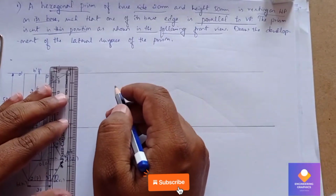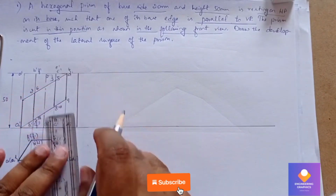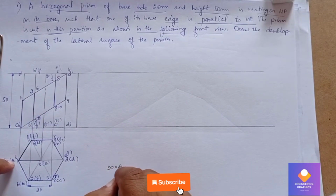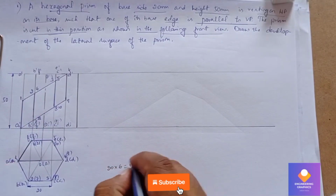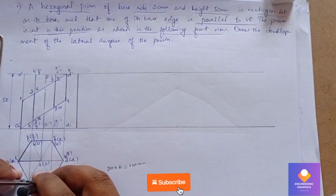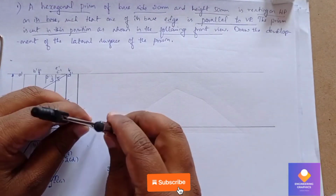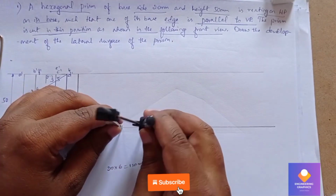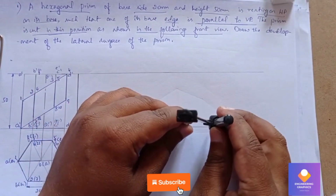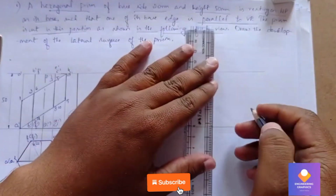We'll draw a reference vertical edge. So here the hexagonal prism of dimension 20. So 20 into 6 sides means it is a total of 120 mm. So that means if we cut the arc by considering 20 mm, total 6 arcs we have to cut here. Measure 20 mm, and cut 6 arcs. Now you draw vertical lines for all these cut arc points.